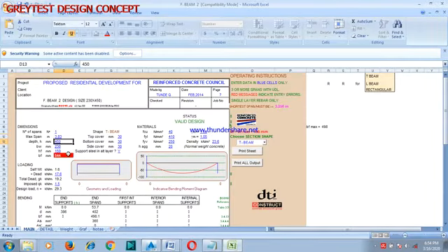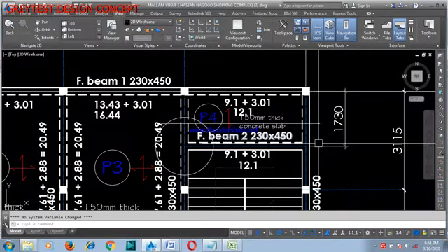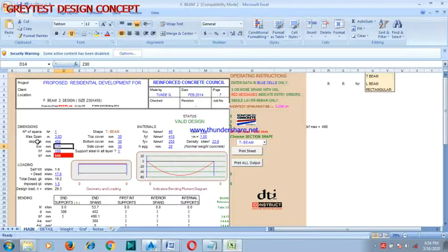Okay, the depth, the BW. Now look at, it is showing you that your BF is not supposed to be 544. That means there is a problem somewhere. Okay, it has already designed it. Now remember that this your beam is actually a T beam. Okay, your beam 2 is a T beam, so that's why it's showing you red here.